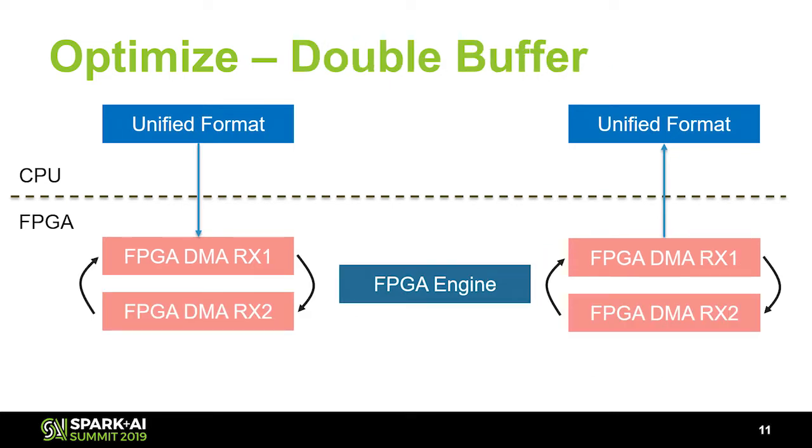If we optimize the data conversion and the data transfer, the ideal solution is to use an integrated FPGA. In that way, the FPGA and the CPU share the same memory, and we don't need to move memory between them. That's the ideal case, but actually we cannot get that. We have to use the FPGA as a PCIe card today, and there will be data movement. But we can solve the problem another way: the double buffer, which we are familiar with. We use 2 buffers. While we copy one buffer, the FPGA works on the second buffer. When the FPGA work is done, or the data copy is done, we switch the buffers and start to work on the next buffer.